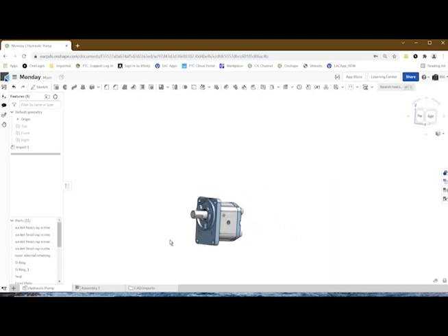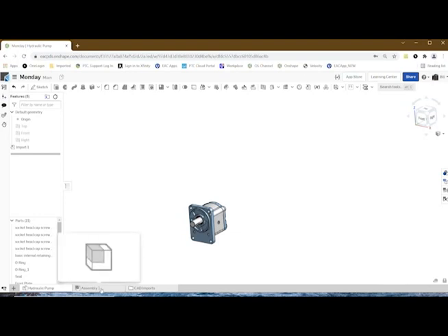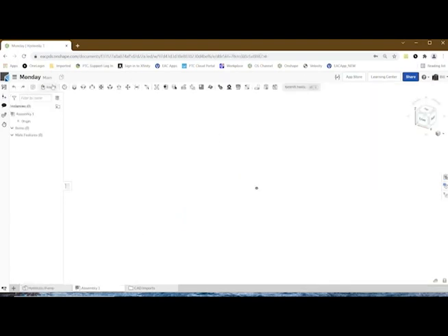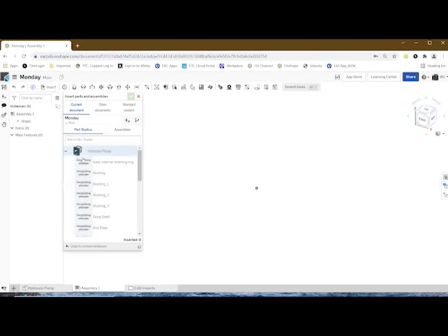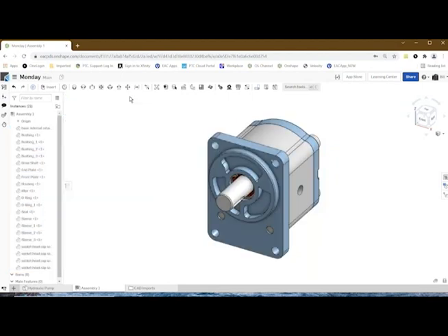So one of the things that we want to do when we look at it this way is it's created all this geometry, all the nuts and bolts and all the components in this PartStudio. If we wanted to make an assembly of this, where we have a bill of material and things like that, I could go to Assembly, and I could say, let's insert this information. So I could insert all the individual parts that were in this assembly, or I can insert the whole thing. And it's not really recommended to do this, but what I'm going to do just to save time is I'm going to say, just bring them all in the whole PartStudio and merge that in.